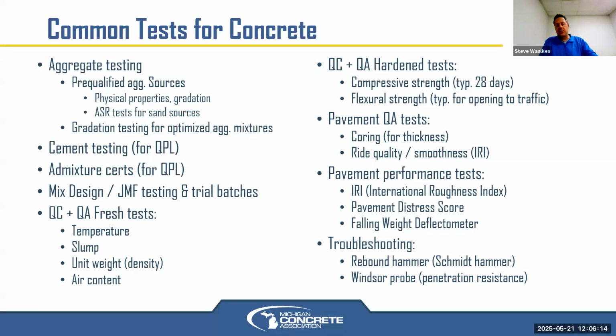But the aggregates constitute the majority of a cubic yard of concrete, and we do a lot of testing on those. If it's a state job or any job that falls under federal highway funding, you have to typically follow MDOT specifications, and a lot of cities and counties and other non-public agencies even reference MDOT specifications at times because they have a pre-qualified aggregate testing program where they test those aggregates.